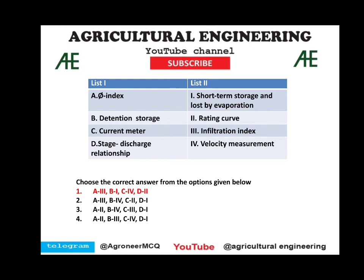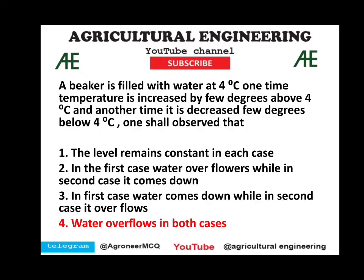So here we have to match the following. The phi index is related to infiltration index. Detention storage is a short-term storage and it calculates the loss by evaporation. Current meter, you should know what is the use of current meter. Current meter is used for velocity measurement, and the stage discharge relationship is given by rating curve.